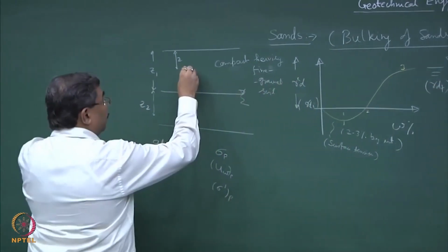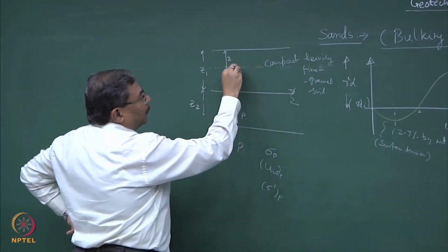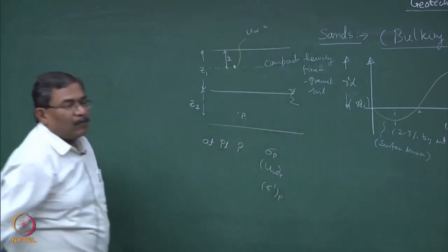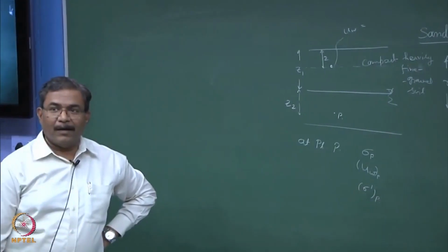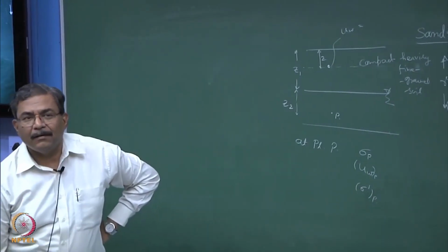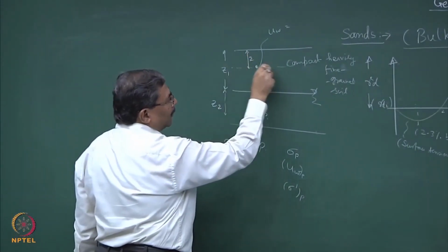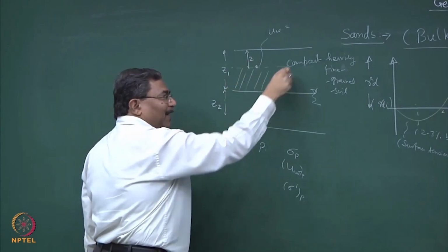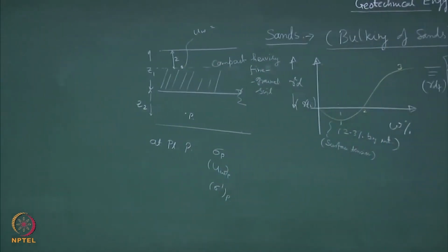You remember the concepts of finding out the pore water pressure here? If this is the capillary zone, you will have to put a tensiometer here, you can compute the UW value. What will be the value of UW? At this point you are trying to find out, this is the capillary zone, this is the peak of the capillary zone, boss. You should remember, this is the capillarity, you will get straight away 0. Apply mind before you are writing something on the piece of paper.